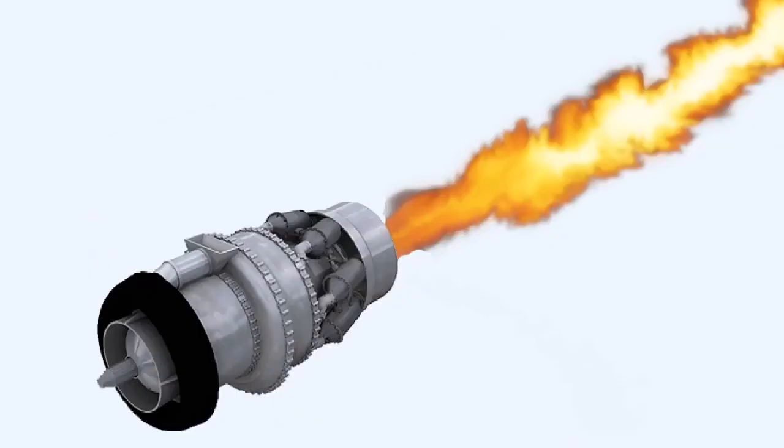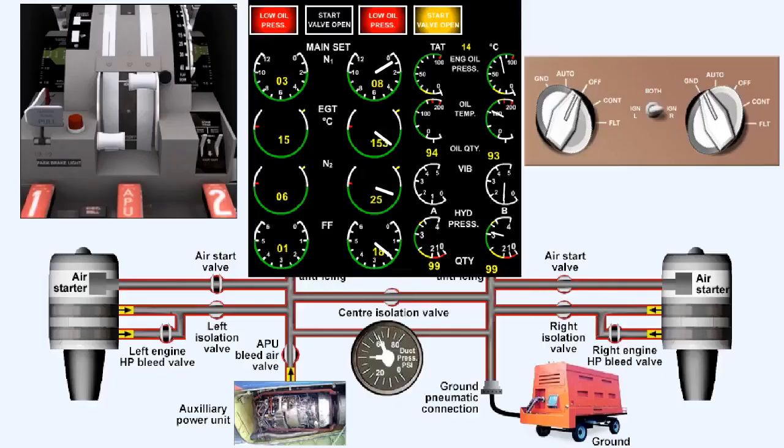Two dangers exist if this fuel is ignited. Firstly, it will cause a very large jet of flame to issue from the exhaust system, the phenomenon called torching. And secondly, the rise of EGT may well be uncontrollable and could exceed its limitation.